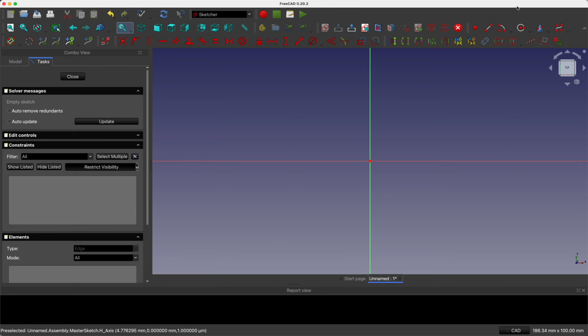And we're going to add a line that rotates around the center point there. So line, center point. Give it a certain fixed length, otherwise it gets really big when you rotate. It doesn't matter what the length is, anything is good.